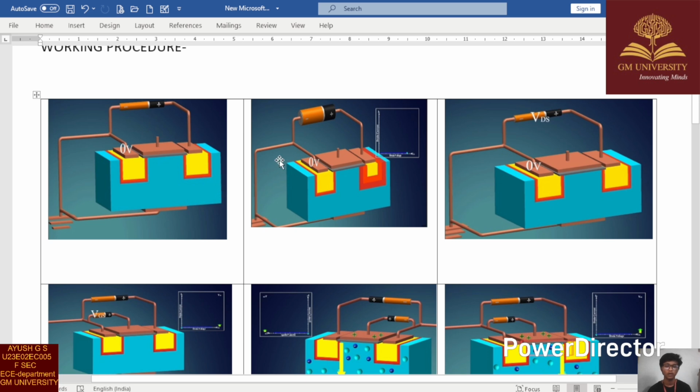When the gate voltage is lower than the threshold voltage, the MOSFET will be in the cutoff region. You can see here the cutoff region is where the graph lies along the x-axis, where we can measure the VDS. Now the first condition we will discuss is VDS, with the VGS constant.